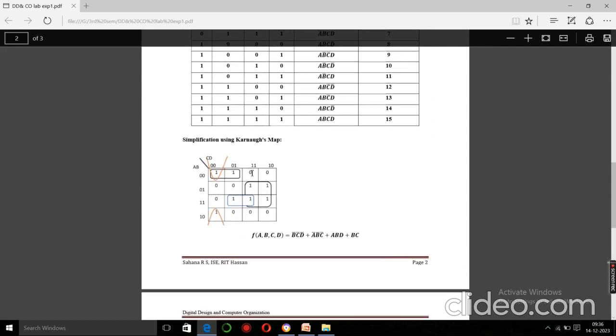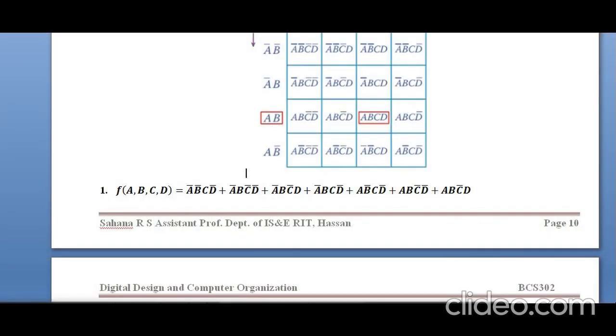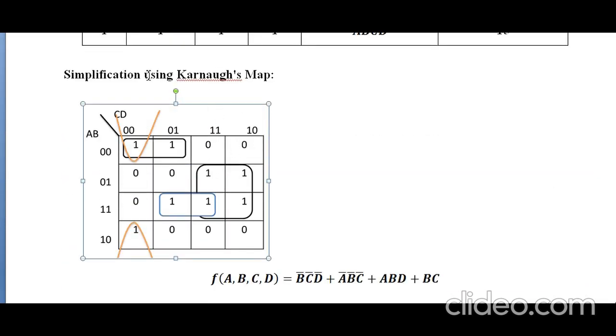So the K-map is shown here. The detailed K-map can be clearly understood by observing this figure. We have to group in terms of 2 power n. We can group 8 minterms together, or 4 minterms, or 2 minterms, or individually we can consider 1 minterm for the equation. In the given equation, if we group the minterms, the K-map will look as shown in the figure.